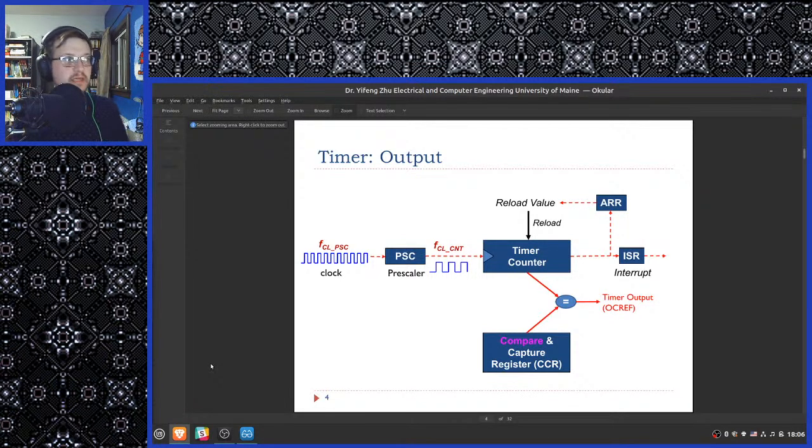So why have a prescaler at all? The answer is the limited size of the internal register of the timer. It's kind of like with floating point numbers: in the same way that you don't need stuff to the 20th decimal point, for practical purposes, timing things on a nanosecond scale is only useful in specific applications. It's not a general purpose application.